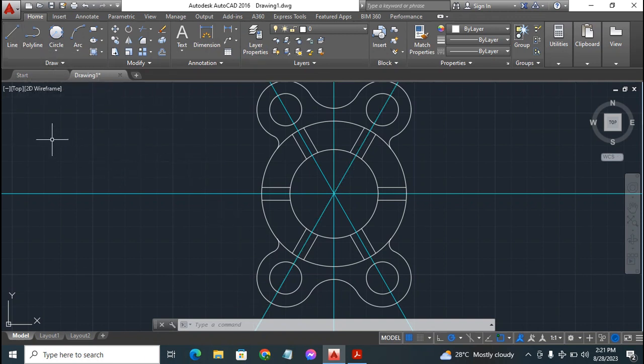Then we can go to the draw ribbon. Click on the draw ribbon, then lock your cursor to this point where you want to draw in that center line, then take it to this center point, then to this end here. Alright, as you can see, we're still wrong, so I'll click on this line to get rid of them. That's not what we need. What we need there is a center line.